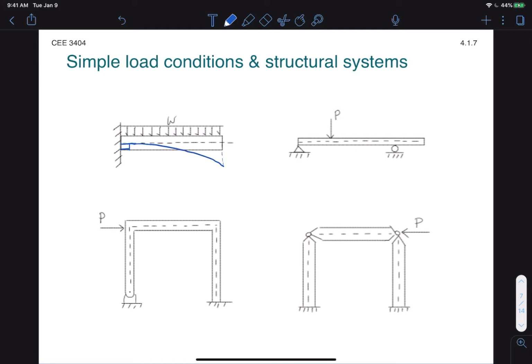Obviously, for most structural beams, these deflections will be relatively small, almost imperceptible, but we of course exaggerate them to make them more obvious. Okay, now let's move to the top right, where we have a simply supported beam with an overhang, and it's being loaded in between the supports. So in this case, because of the downward load again, this will induce a negative curvature.